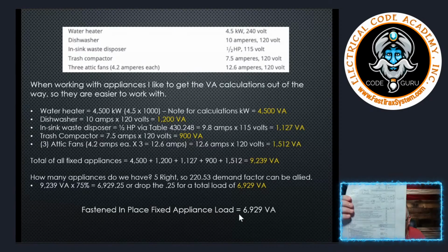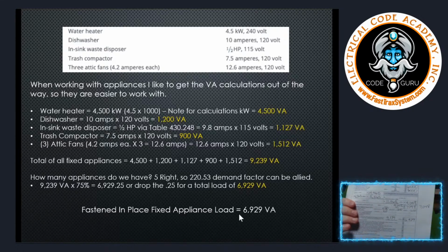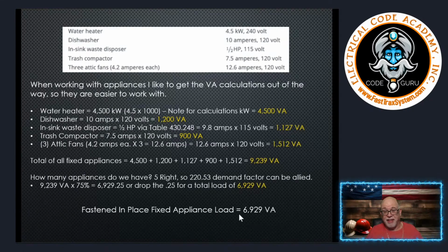Now, you might say, let's move on to the dryer. But remember, while we're going down this list, we're working on that neutral at the same time. I love to work at the same time. So when you look at these loads here, notice something. There is only one of them here that utilizes no neutral. That is the water heater. Water heaters do not use a neutral. It's just a heating element.